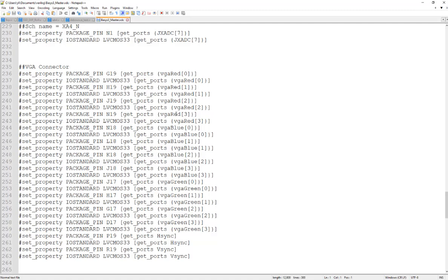Sometimes the bright red, sometimes the dim red. Okay, so the red has intensity, right? If you have a super strong red and you mix it with other colors, it turns into a different color. So you want to resolve the whole red color using different intensities or brightness of the red. And you are using 4 bits to resolve it in theory, okay? So you do have 4 bits to resolve it on the FPGA.